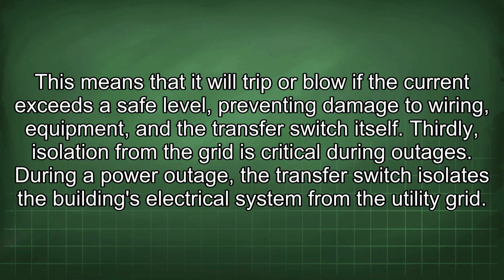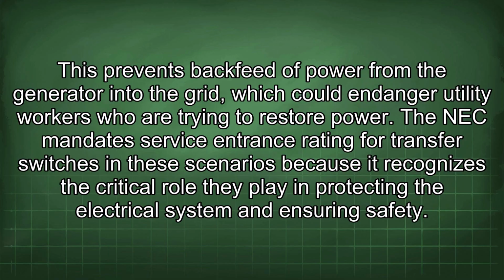During a power outage, the transfer switch isolates the building's electrical system from the utility grid. This prevents backfeed of power from the generator into the grid, which could endanger utility workers who are trying to restore power. The NEC mandates service entrance rating for transfer switches in these scenarios because it recognizes the critical role they play in protecting the electrical system and ensuring safety.